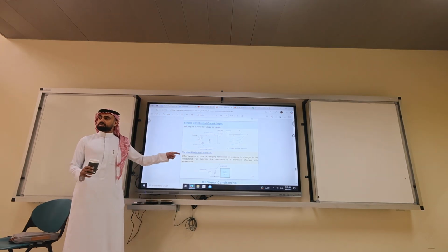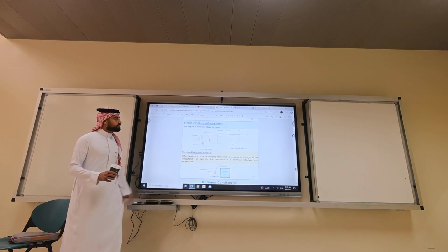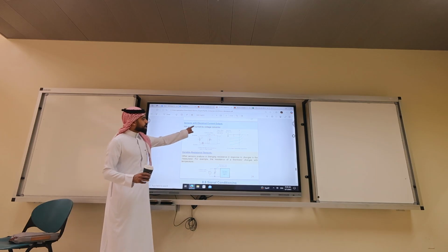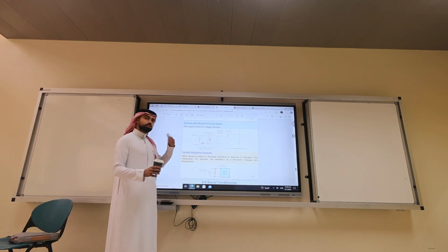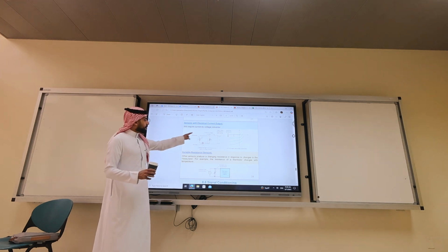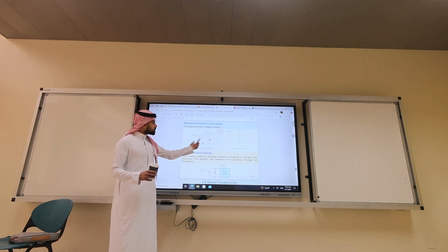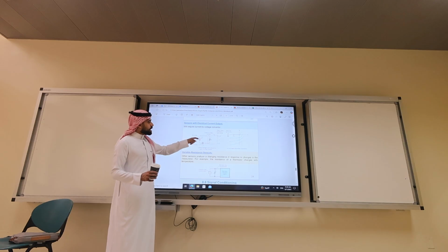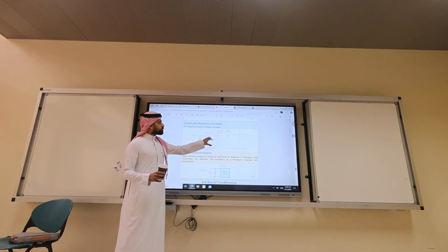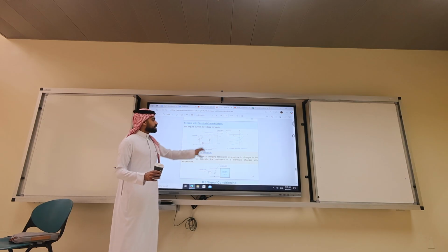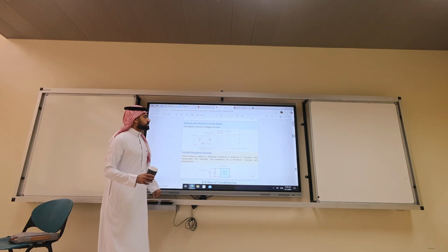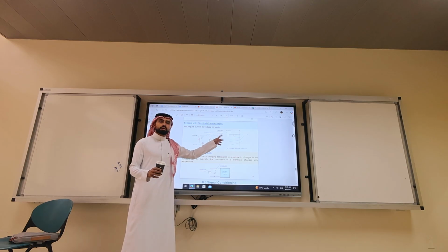So diodes are used inside sensors in that case. We will require a current to voltage converter. How do we do it? It's not required, but with this circuit, we have excitation, we have a diode, and then we have the current to voltage converter, and this system should give you a voltage. What's the output? Voltage.